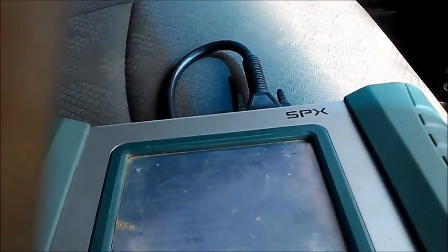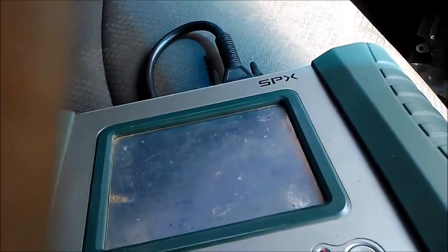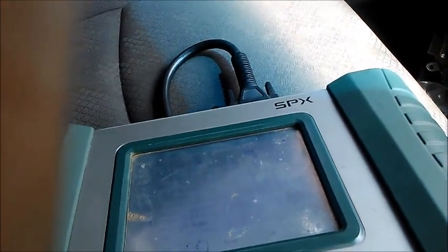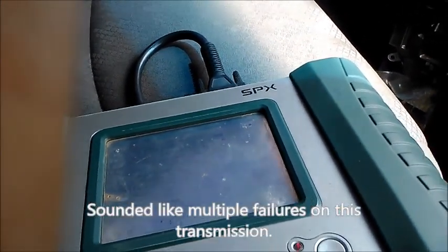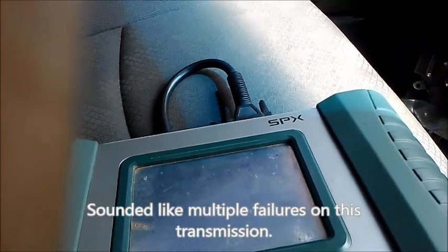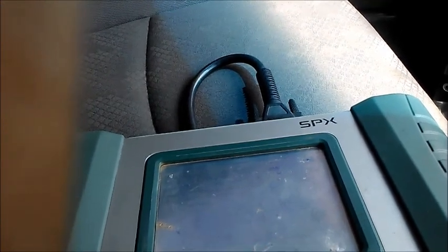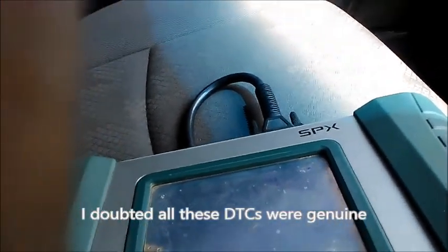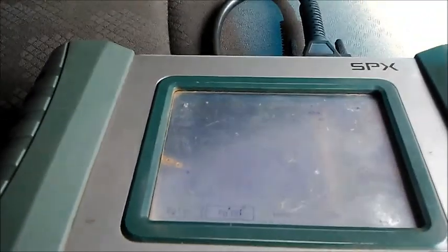Okay, this is kind of interesting. What this would mean is there are multiple issues in the valve body of this gearbox. There are multiple electrical issues. It mentions solenoid 2, it mentions the temperature sensor. For all of these to respond at once, most likely there is a problem in the harness from the gearbox computer down to the valve body, to the shift solenoids and that temperature sensor.